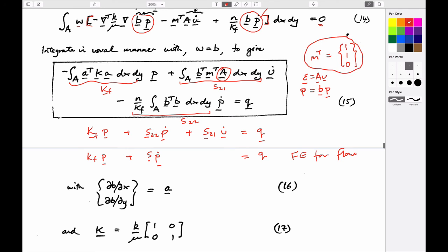So those are the 3 matrices. And physically, all this is saying is that if you displace this by some amount, it squeezes a certain amount of volume into the system. And it acts as a volume source that then has to be redistributed. It can be distributed in two ways. It can be distributed by flowing out of the system really quickly. If this is big, it will just dissipate. If this is not big, then the other alternative it has is it builds up pressure. So you squeeze it, pressure will go up because it can't get out quickly enough. So that's a useful way of thinking about it.